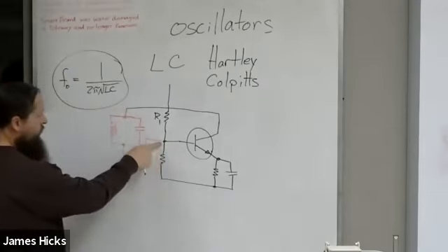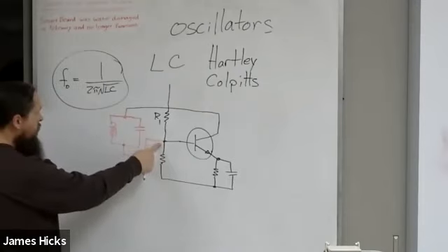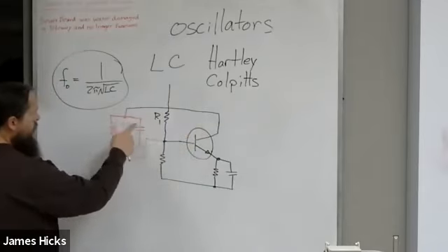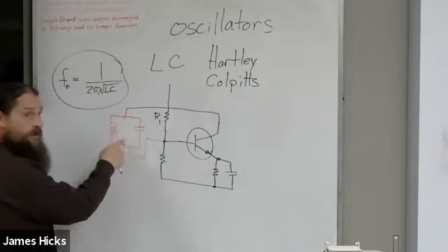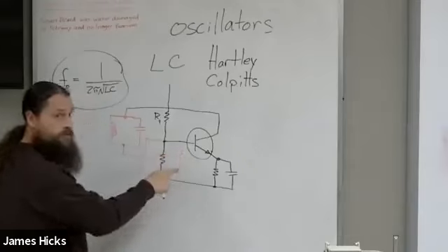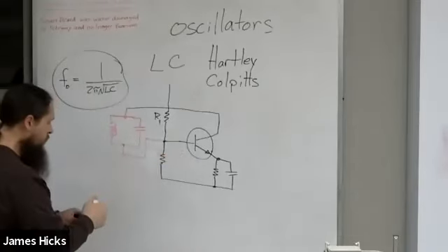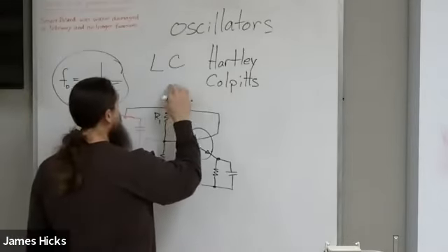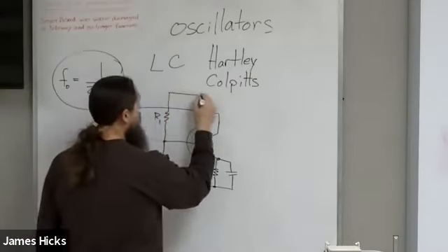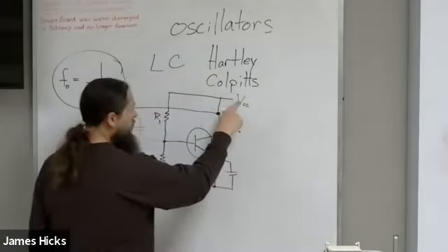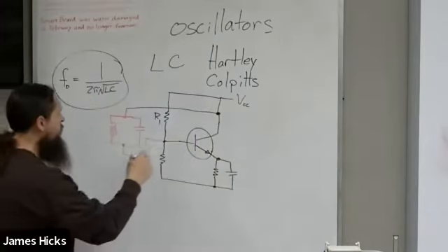That's going to this base input. So I'm going to feed back the collector output through this LC tank circuit back into the base. So that's going to give me my positive feedback. And then there's my VCC power supply.